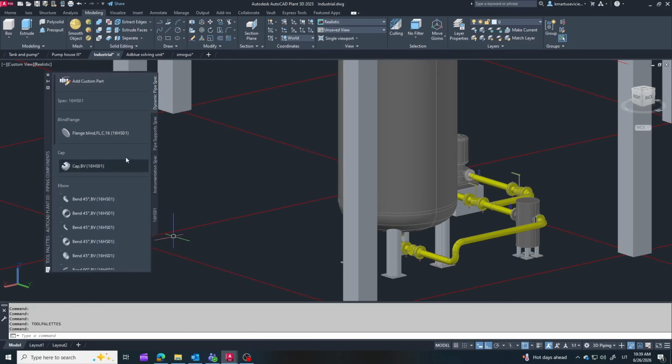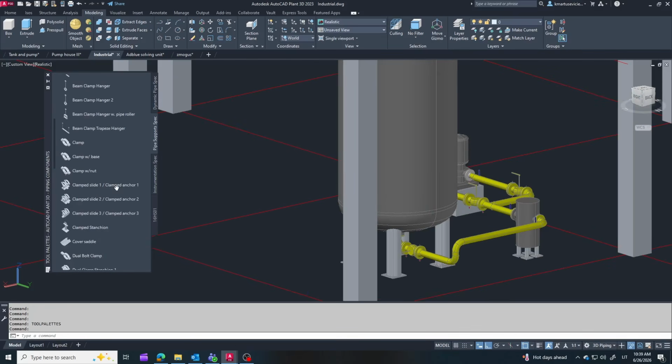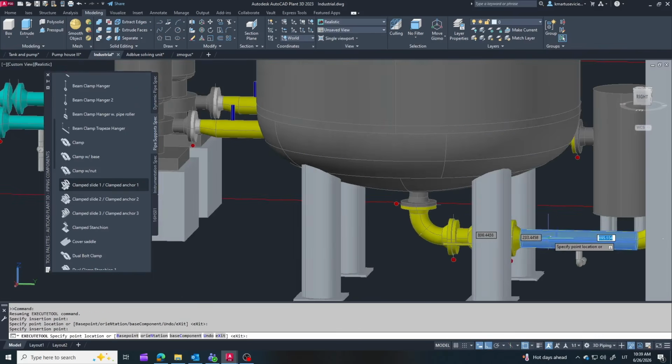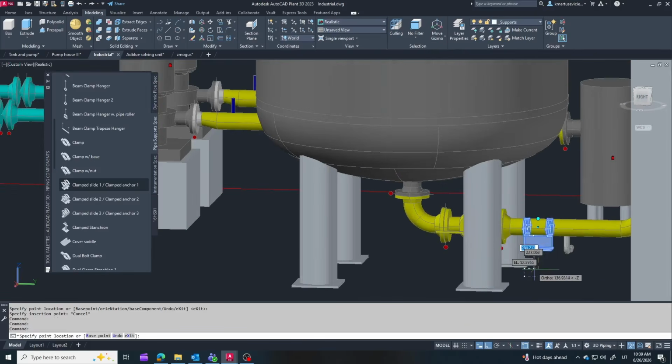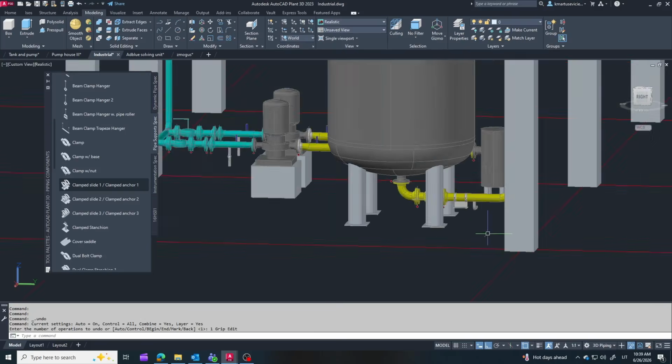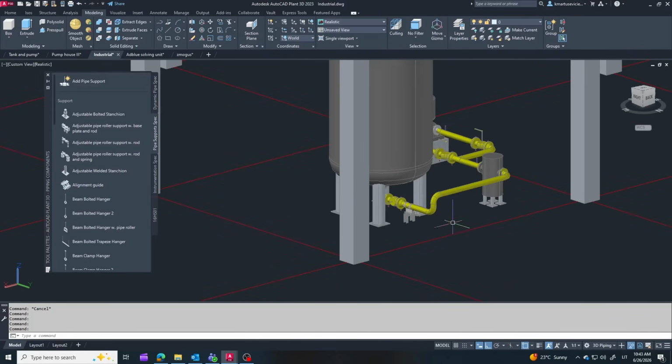Now let's move on to pipe supports. My advice is simple. Don't just support the pipes, also pay attention to heavy components and equipment nozzles. Good support placement protects the equipment and improves the long-term reliability of the piping system. Every pipe support needs something to support it.